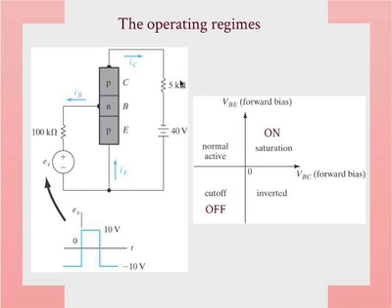You have a circuit, and that's a very common circuit, so you can keep that picture in mind as well. You can think about the operating regimes as four quadrants, and they are based on the base emitter voltage. So you have two PN junctions, right? Like I said, it's based on whether each PN junction is forward biased or reverse biased.